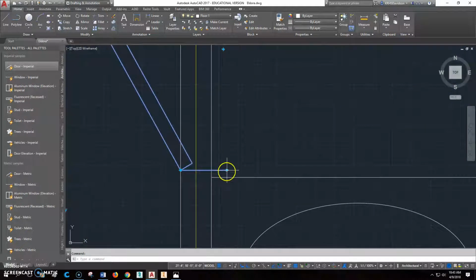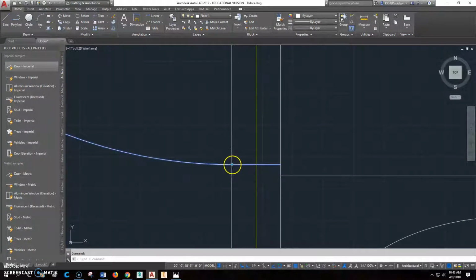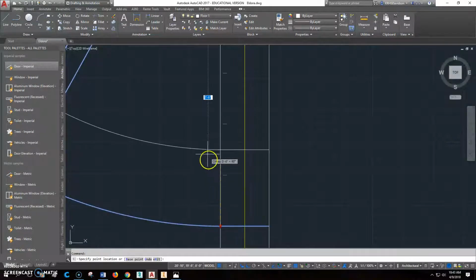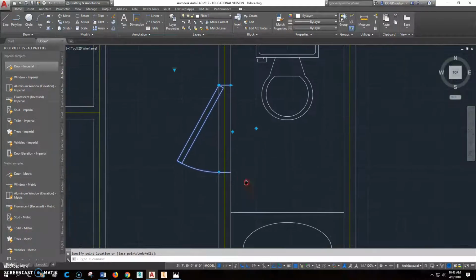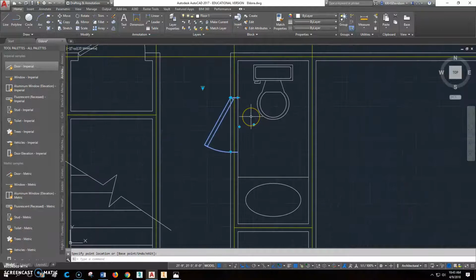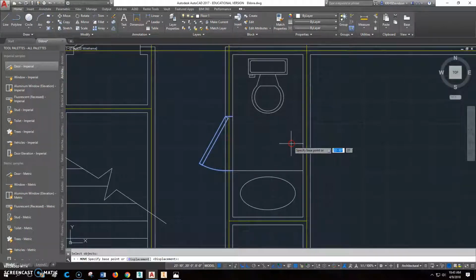We'll change the wall width back to 4 inches. Probably change it this way. And let's change this so this is a smaller door. A 3-foot door is big to get into there. 2'4" is probably a great door for something like this. This is where it gets kind of strange. Let's go ahead and click move. We're going to move this down this way, and we'll move it up 4 inches.